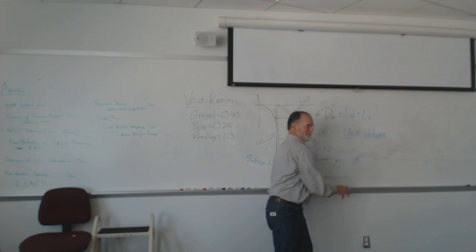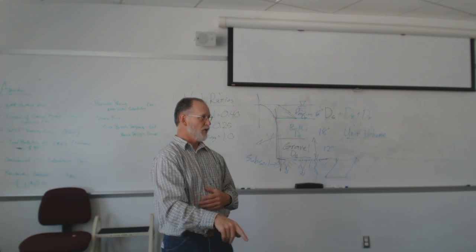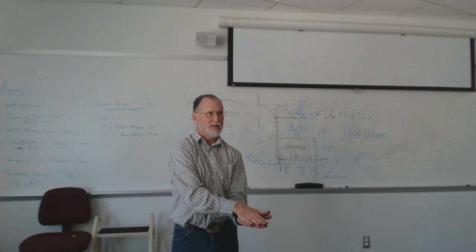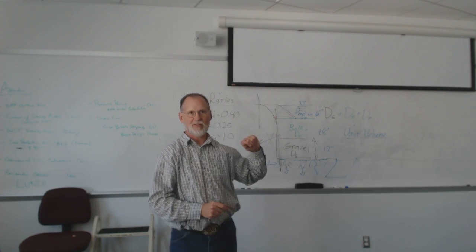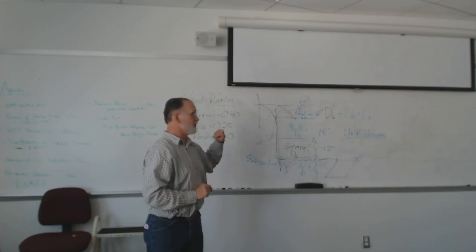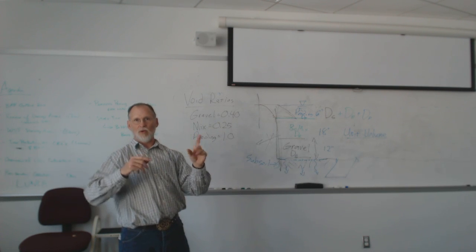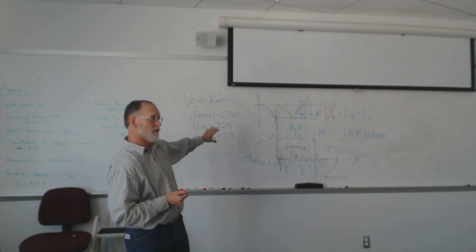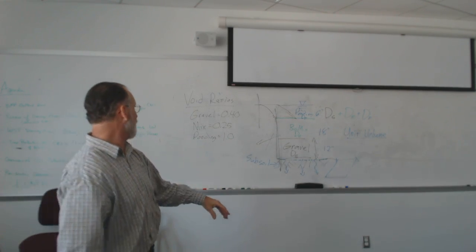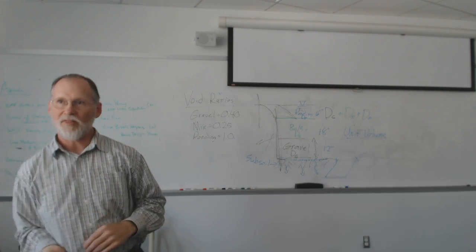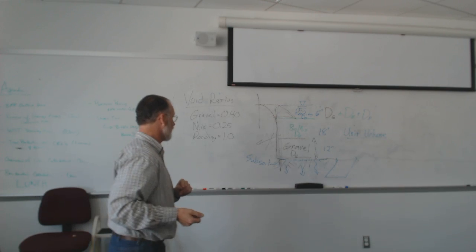If I had a plexiglass column here, 1 foot, flat bottom, with clear sides, I can fill it up to whatever height I want with these different mixes. And I know my void ratios, so that is my unit volume. So I know 1 square foot of rain garden will hold a certain amount of water. Then I can do one calculation. I know I have to hold 1,000 cubic feet of water. What's the square footage of my rain garden? I do one calculation.